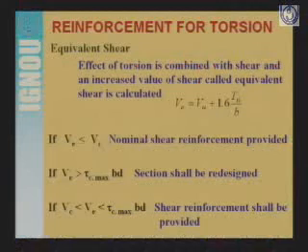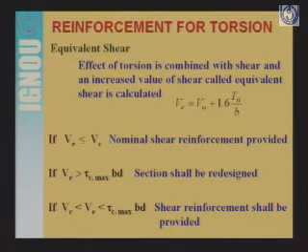So similar to the earlier cases, three cases are given here. If equivalent shear Ve is less than or equal to Vc, then as we did earlier, we will provide nominal shear reinforcement. And we will see how to proceed with those expressions.